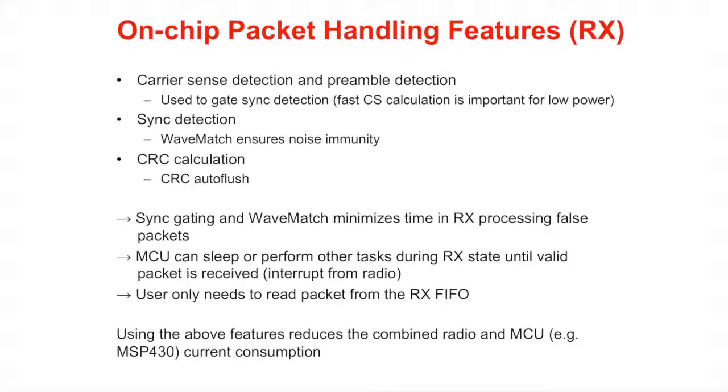If the receive signal qualifiers are integrated in the radio, false error check can be done without MCU intervention. Put MCU into low power mode and wait for an interrupt that a valid packet has been received to minimize current consumption. Transceivers from TI have digital output pins, which generate an interrupt to the MCU if a packet has been received with OK CRC.